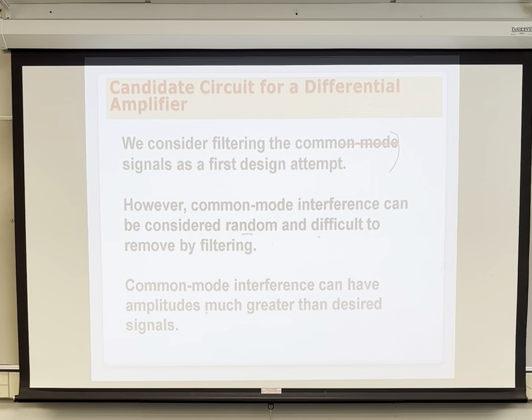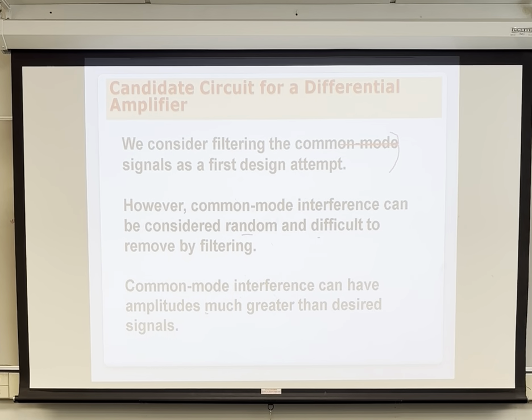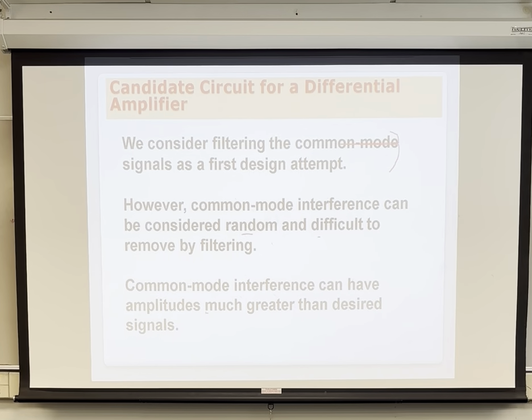It's very high level. It's electromagnetic waves, so it's not visible, but it's everywhere, and on everything. If you go outside, you still have common mode because of all the cellular and communication waveforms. But in here, 60 hertz is a very large common mode signal. If you wanted to reject 60 hertz, this circuit has to be capable of rejecting it, even though it's very large, several large voltages, and it can be random.